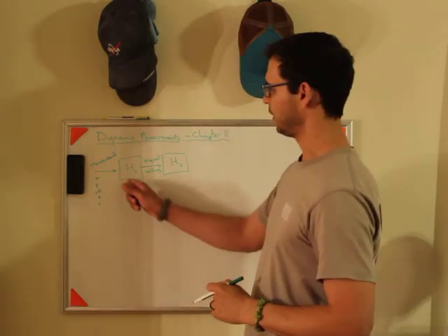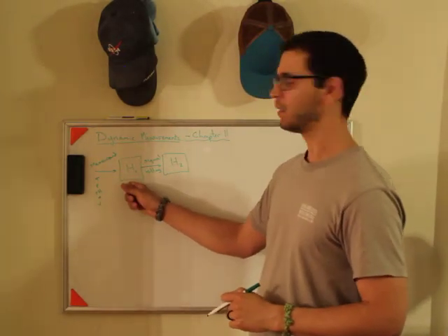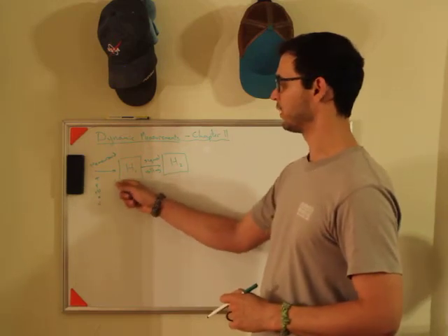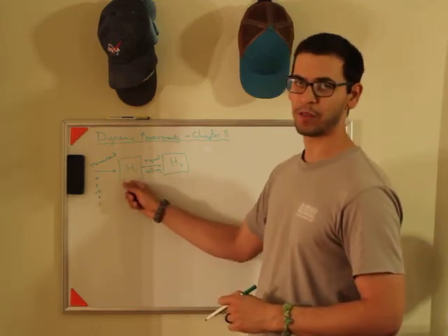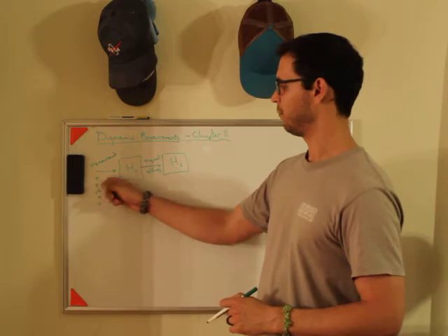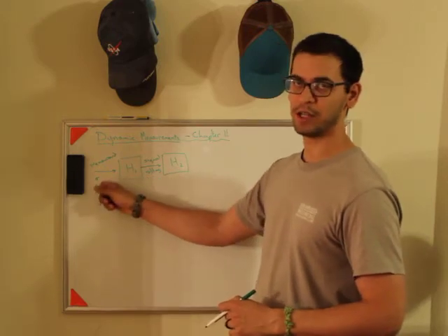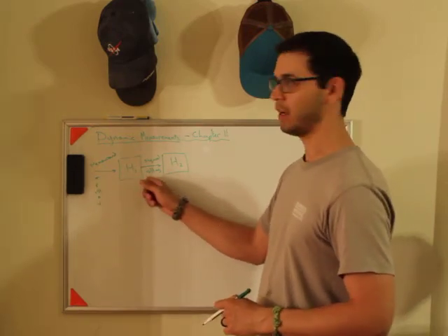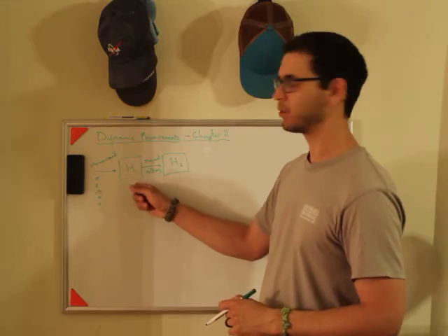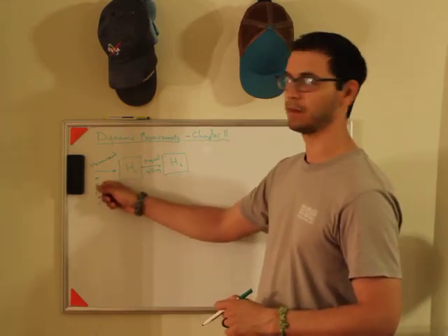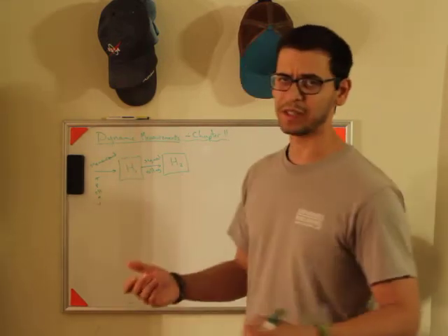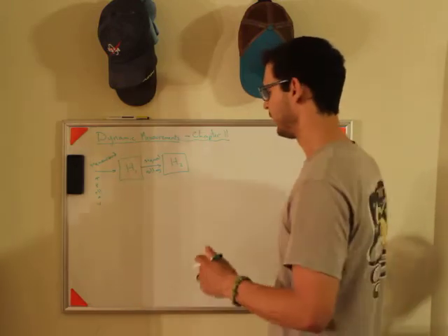Okay, and so you have like your actual sensing element that responds to it. So like if you have a thermocouple, right, the voltage is going to change based on temperature. If you have a pitot probe, you're going to have a pressure transducer where the voltage is going to change based on pressure, which is really a strain gauge, but anyway.